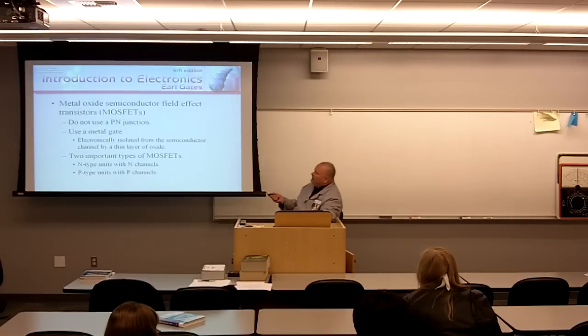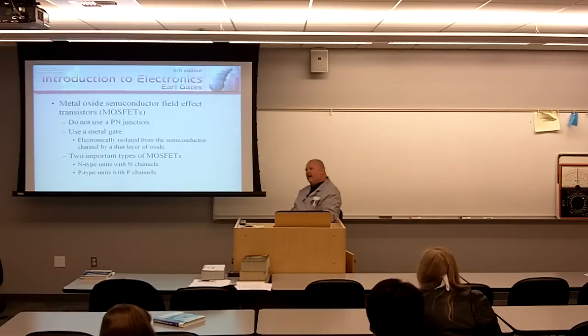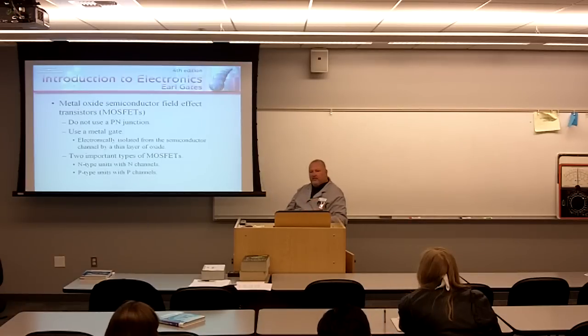I want to warn you, anytime you hear electronically isolated, electrical isolation allows you to build up different charges on different things. That's what isolation does. By doing so, these components are much more prone to damage. We're going to talk about that more in a bit. Damage from electrostatic discharge, ESD.